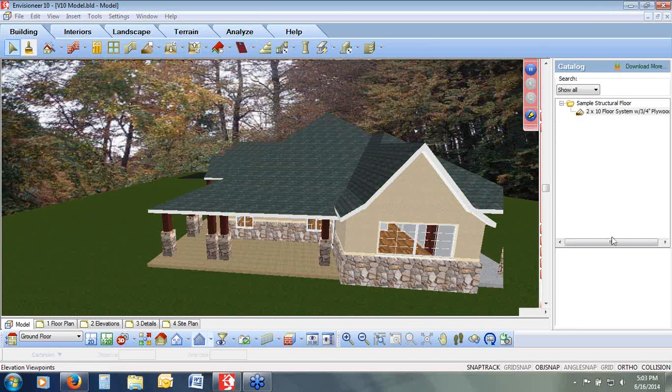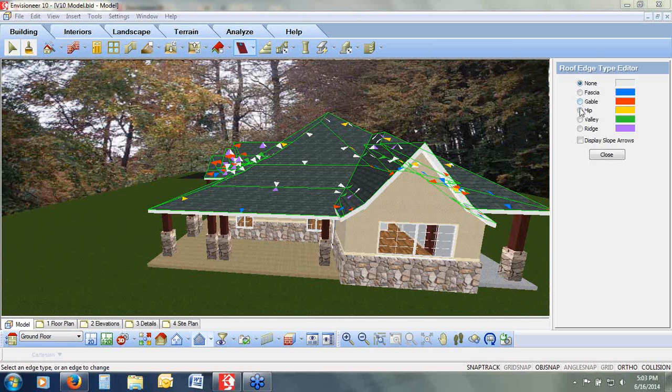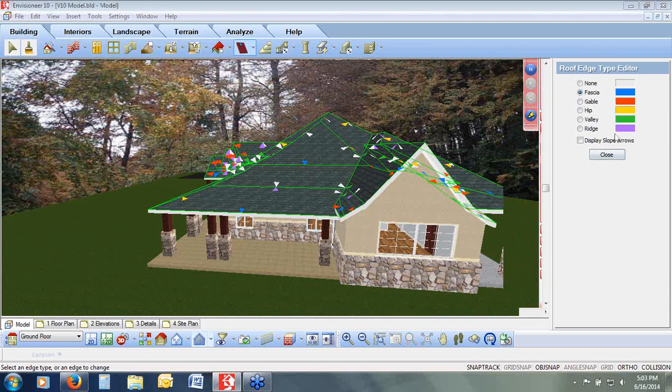And roof edit mode. Is this like roof surface settings? Yeah, so if I go to this editor, that allows me to go to each of these sides and change it to a different setting. So if I click on that and I want to make this into a ridge line, I can come over here and say that that's a ridge line. Or put it as a fascia and click on the arrows that I want to change to a fascia. So yeah, that's like changing and editing the roof surfaces mode. You're exactly correct. All right, the valley framing, that's correct.